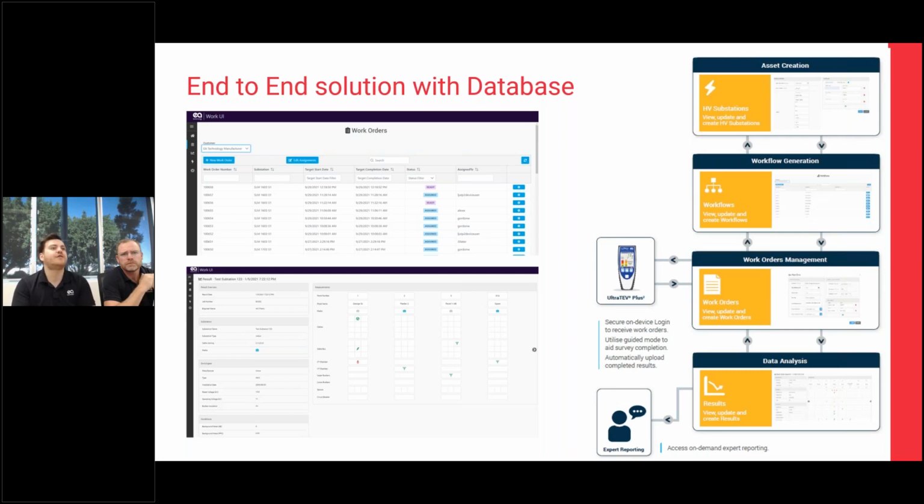One of the most powerful features of this is the consistency of the data and the automatic trending that takes place on the cloud. So now if you have taken multiple readings across multiple years, you can actually compare all of those readings quickly and easily, all in the one place and on the one screen, rather than jumping between all of the different survey files, which we've done traditionally in the past. So this is a really great tool that not only allows us to capture and grade things based on the amplitudes, but keeps all of the phase plot and audio file data that we use for more in-depth analysis and decision making.